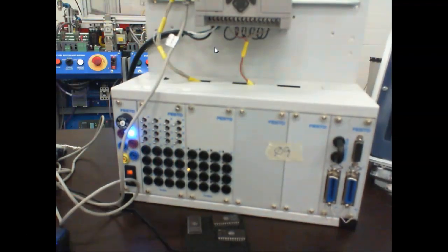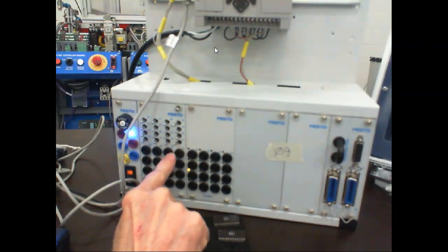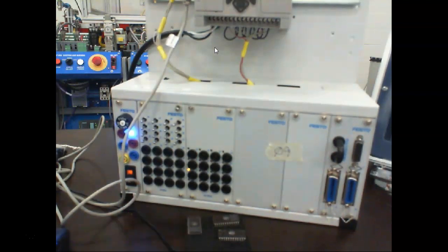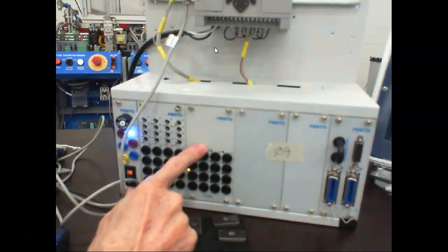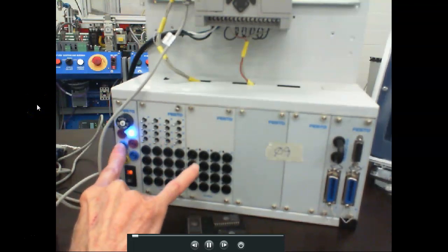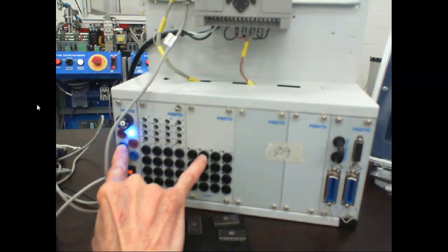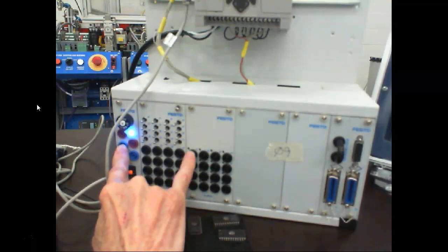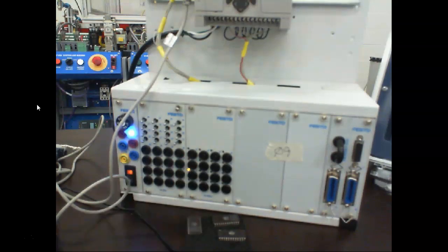So we'll say turn on motor 1, and if we assign it to this output right here and it comes on, then that'll assign it off. But in actuality, you would have to hook the motor up from this blue one over to here with the motor in the center. And then, of course, not necessarily the motor. It might be the relay that controls the motor. So very seldom do we run motors directly off the PLC. Normally what we'll do is have the PLC pick up a relay, or energize a relay, I should say, and then the relay runs the motor.